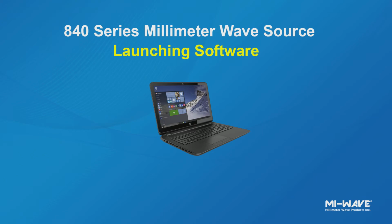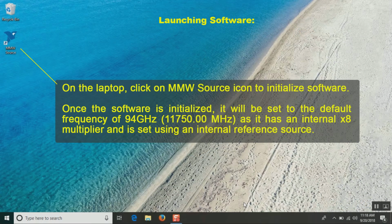Let's launch the laptop software. On the laptop, click on MMW source icon to initialize the software. Once the software is initialized, it will be set to the default frequency of 94 GHz or 11750 MHz, as it has an internal ×8 multiplier and is set using internal reference source.